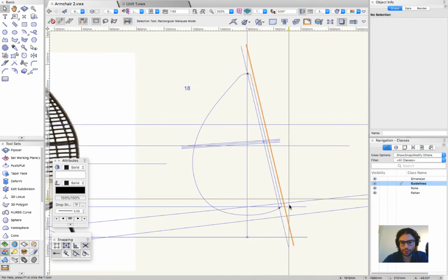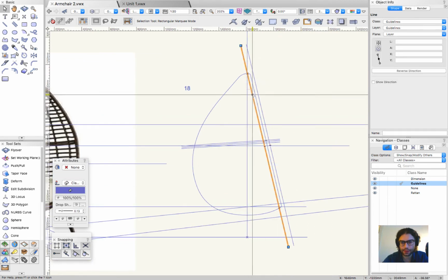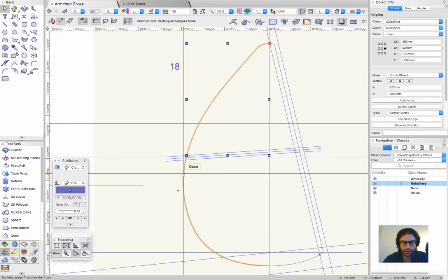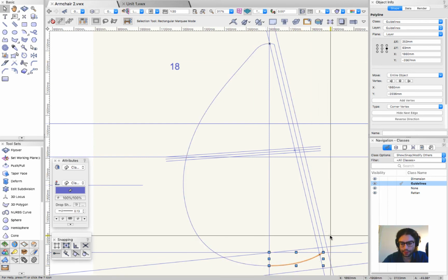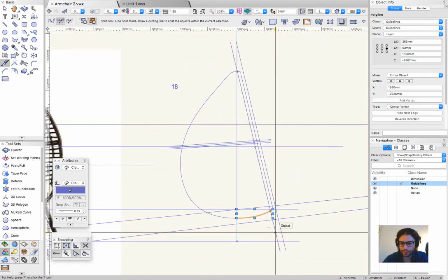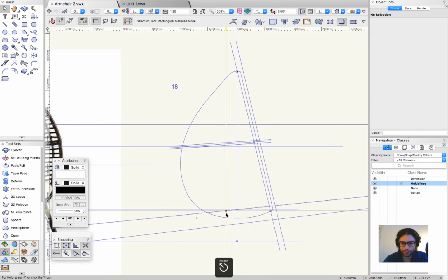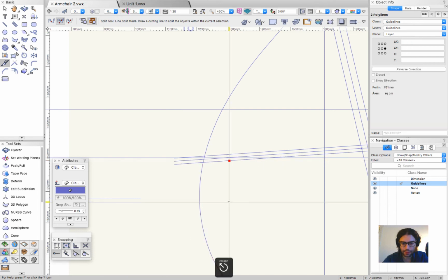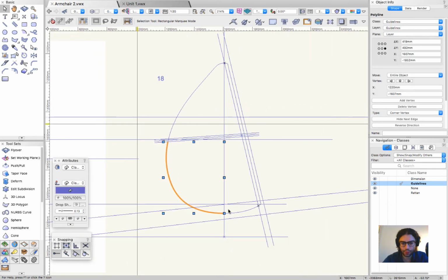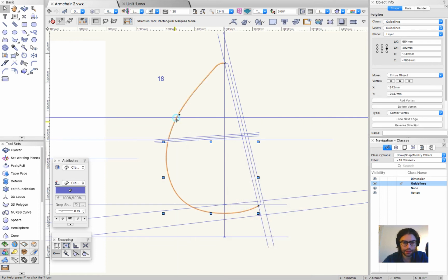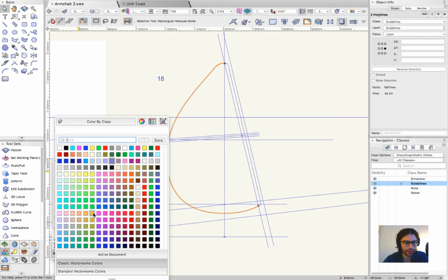I mean the loop the first, so the border starts here, so we don't need to cut anything here. Let's cut this one. Later we will need it for the bottom part, and also let's cut it at the previous one and connect two parts together using the compose command. Let me highlight them using a different color.